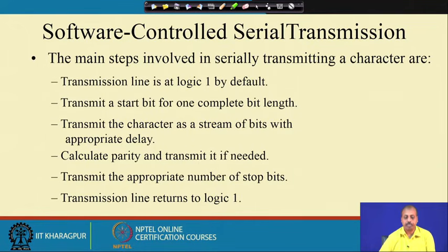So it will calculate the parity, and the parity has to be 0 or 1. Based on that it will be sent, and then it will transmit the appropriate number of stop bits, and then the transmission line should return to logic 1. So this is the flow of any software routine.